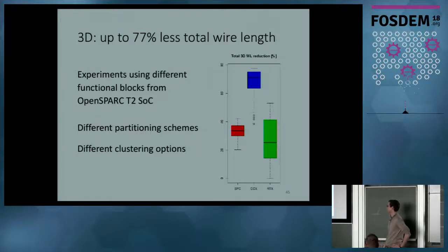It also widely depends, even for the same design, on the clustering grain that is used, and also on the objectives we set for the graph partitioning. Do we want to reduce the amount of nets crossing in 3D? Do we want to reduce the total wire length or maximize the total wire length that is cut? All those kinds of objectives will impact the gain in the end.